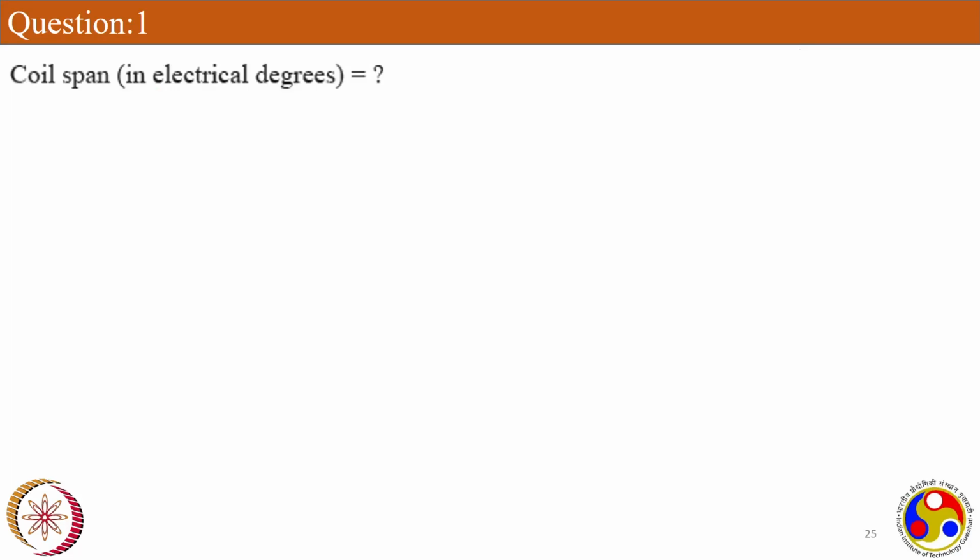The coil span we just calculated is 150 degree. Beta, you know that between each slot is 15. Coil span is 150. Next one is pitch factor Kp for third harmonic. Kp is cos 3 epsilon by 2. We just saw epsilon is 30, it is short pitched by 30 degree, and cos 3 epsilon by 2 for third harmonic.